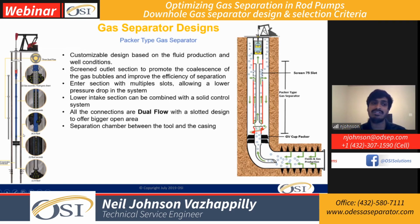Now, the way it helps in the overall gas separation efficiency is that suppose the pump has a pump off controller, or the reservoir conditions or the pressure is not high enough. This storage sump, having that much additional fluid stored, helps not to run the pump dry, right? So let's put some numbers: suppose we have a pump running at 7 strokes per minute, lifting about 100 barrels per day.